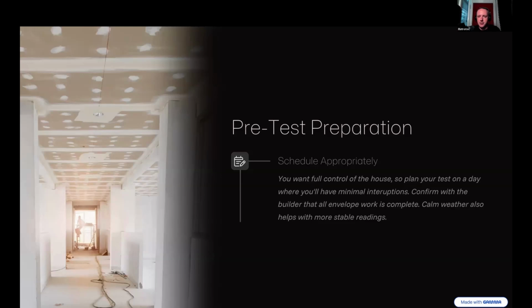Whether on the roof deck, you can do the Monopoly style framing where you don't put on the eaves yet. Those eaves are just bolted on later. So your air barrier goes up the wall and then up the roof deck. A lot of times we see builders use zip system or something like that to create that air barrier. It's called a Monopoly style house because if you look at the Monopoly piece, that's a house. That's what it looks like. There's no overhangs yet. Those are added on later. But at the finished product, you would never tell. It would just look like any other house. It just has a really great air barrier with a fully conditioned attic space. But yeah, you can do that too.